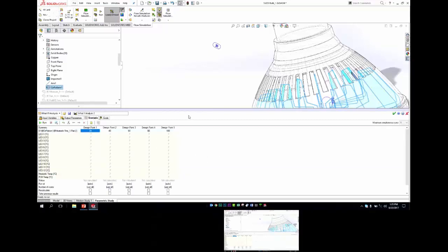And you'll notice now I have a scenario list. It says, okay, these are all the different parameters, these goals. These are the different designs, 20 through 100, and it's going to run all these solutions and then fill in all of where these question marks are. What are these maximum values for the LED, heat chip or heat sink, and PCB temperature? Pretty cool stuff. So obviously I've already ran this.